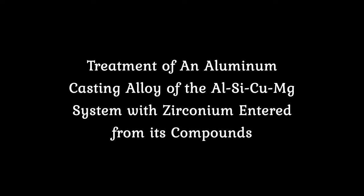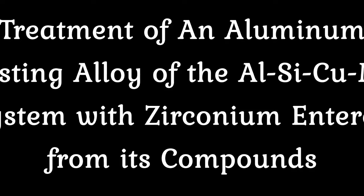Treatment of an aluminum casting alloy of the Al-Si-Cu-Mg system with zirconium entered from its compounds. The choice of a flux that contains zirconium and is intended to harden the aluminum casting alloys has been justified. The microstructure and mechanical characteristics of an aluminum casting alloy of the Al-Si-Cu-Mg system, reinforced with zirconium, have been investigated.